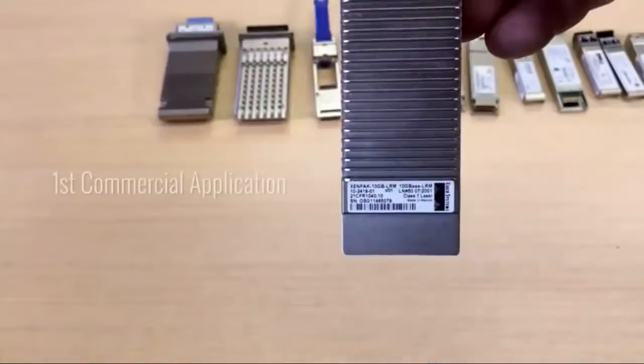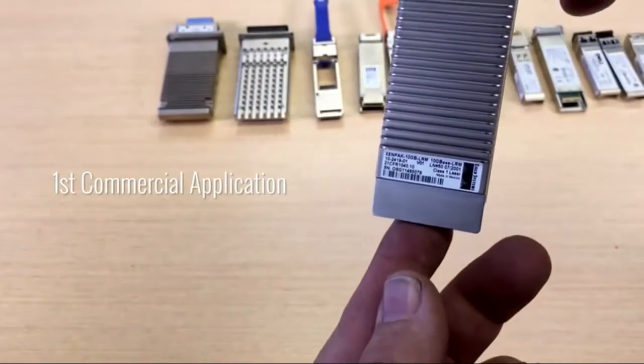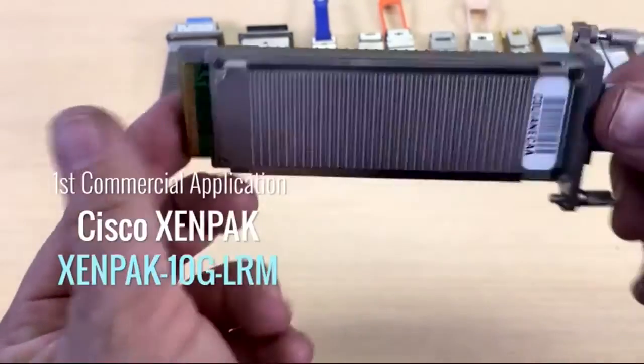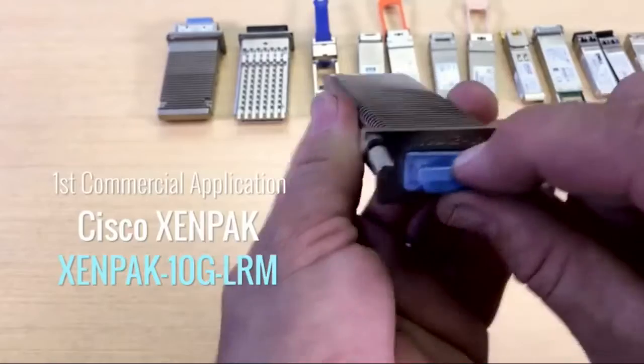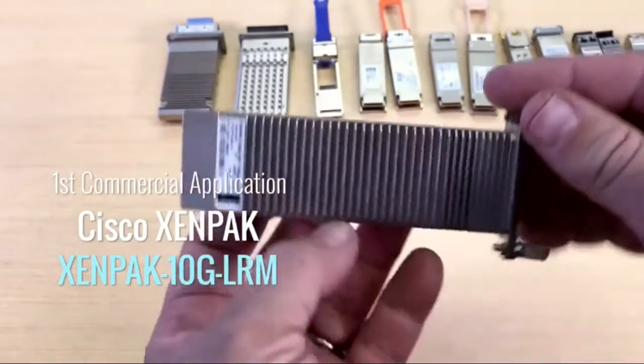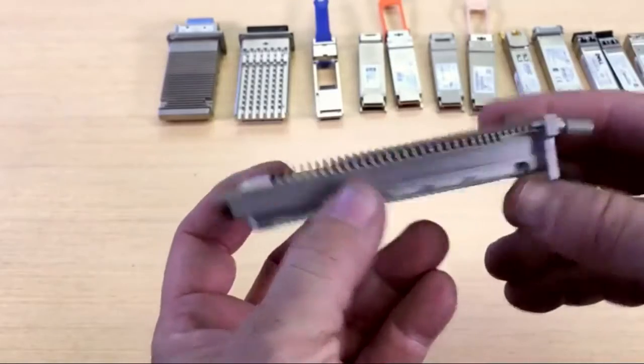Let's start by taking a trip down memory lane. The first real commercial application was the XENPAK, which was developed by Cisco, and it was a larger form factor optic that allowed for more power to come through into the transceivers. You can see the size of the heatsink and how big it was. Current 10 gig optics still just use this small form factor. So they've dropped from a package that would dissipate 10 to 15 watts all the way down to 2 watts now in this small form factor.